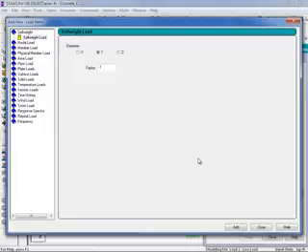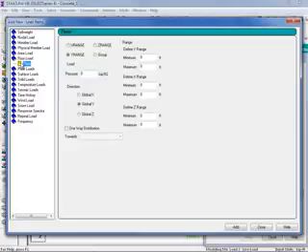And for this load case, I'm going to be defining a floor load and some uniform plate loads. Over in the left pane, I'm going to select my first load item, which will be a floor load. Now this will be used to apply a panel load, which will be distributed to surrounding beams based on a one-way or two-way distribution. The first thing I'm going to enter is my pressure. Again, I'm going to enter this as a negative value to indicate that this is a downward acting force. I'm going to enter the magnitude as 0.05. I'm going to also select the direction as the global Y direction.